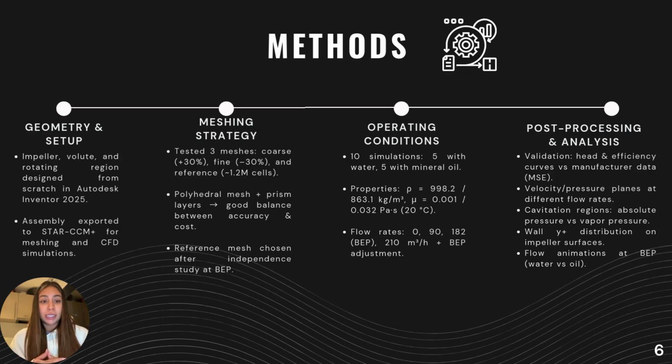Finally, post-processing, including validation of performance curves against manufacturer data, visualization of velocity and pressure fields, cavitation analysis, wall y-plus distribution on the impeller, and flow animations to illustrate pump behavior under real operating conditions.